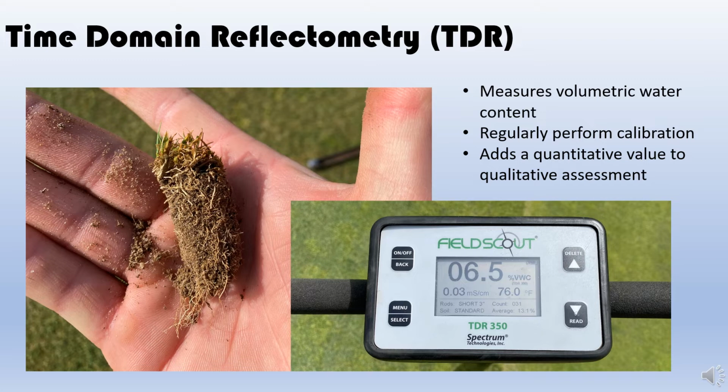For example, we see here a soil core that I took, and this is from a dry spot, and when I stuck the meter in right next to where I took this soil core from, I got a reading of 6.5% volumetric water content. Therefore, I know that the meter is providing a reasonably accurate assessment of the soil quality. So for a little bit, I can just use the Field Scout to get a measurement, or I can continue taking soil cores and doing my visual qualitative assessments.